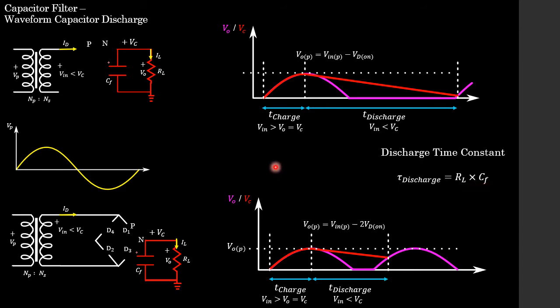So students, to recap what's going on in this slide, this is the capacitor discharge phase. During this phase, we replace all our diodes with an open circuit because we know they are reverse biased. Why are they reverse biased? Well, they are reverse biased because our capacitor filter holds the voltage across our load resistor, and while it holds the voltage across our load resistor, it slowly discharges it from that point.